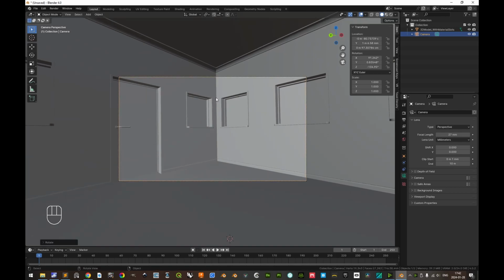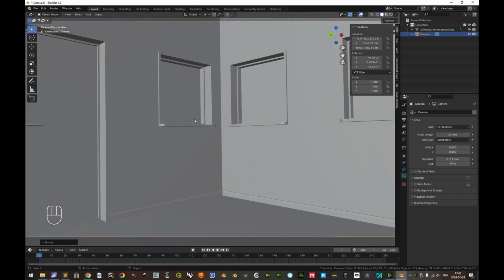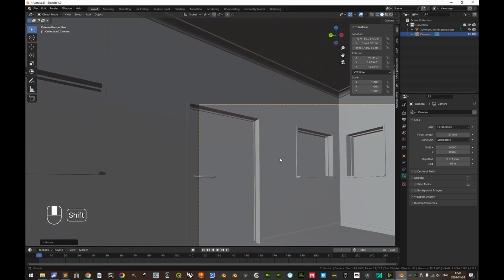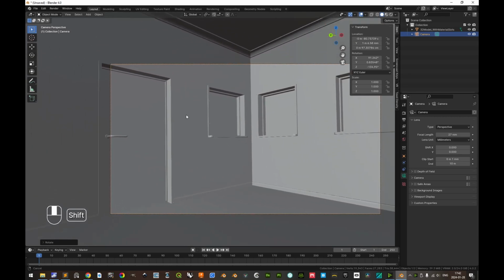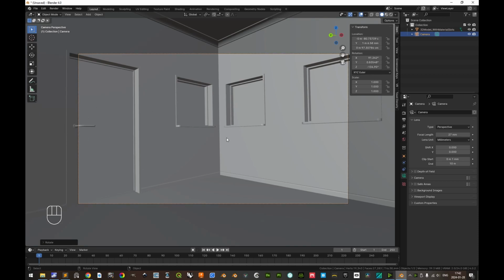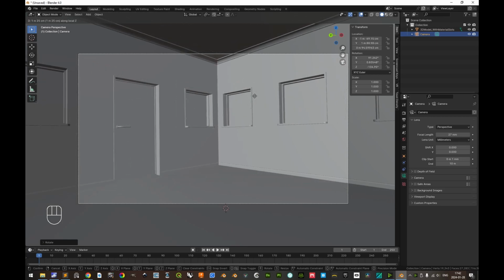And now, in this camera viewport, we can also zoom in so as to get a closer look of what is inside. And we can also hold Shift and middle mouse button to look around here at what can be shown outside of the camera frame. I think that we would really like to go backwards a little, to dolly backwards. So we'll press G for grab and move. And then the local Z axis should be the forward vector here. So we'll do Z and Z. Then we can go backwards here. Very good. And we can go backwards until we are perhaps here.